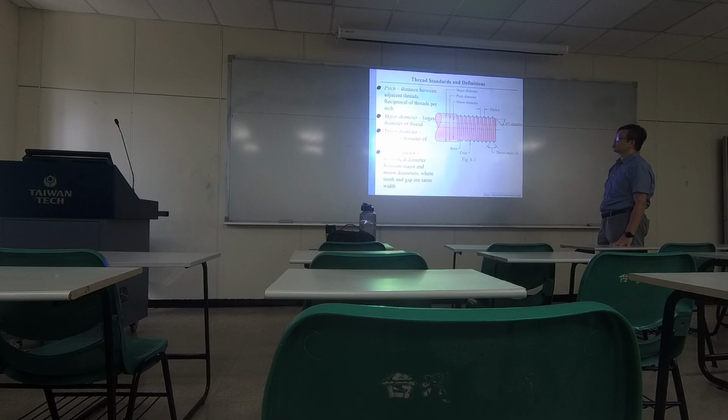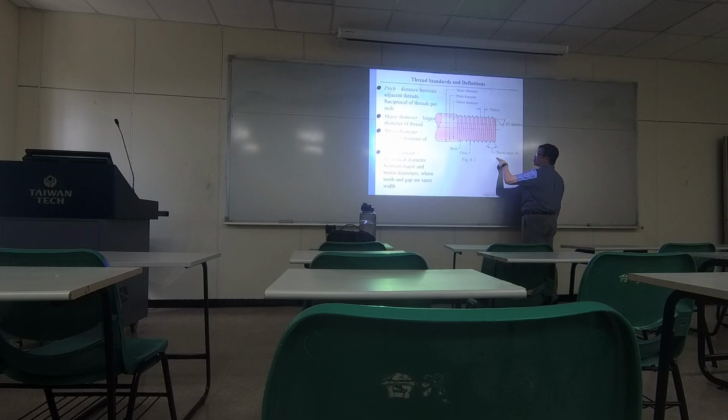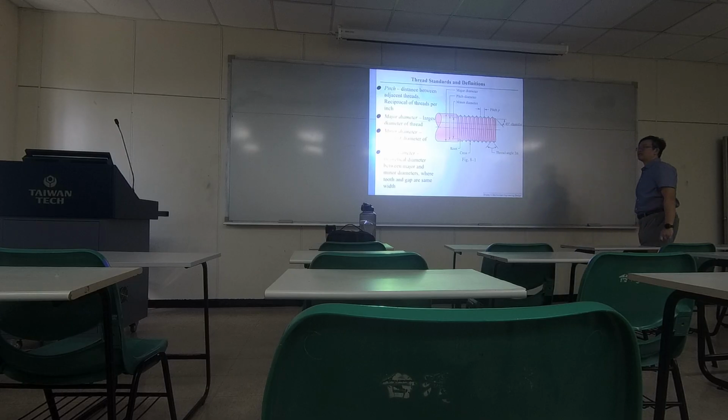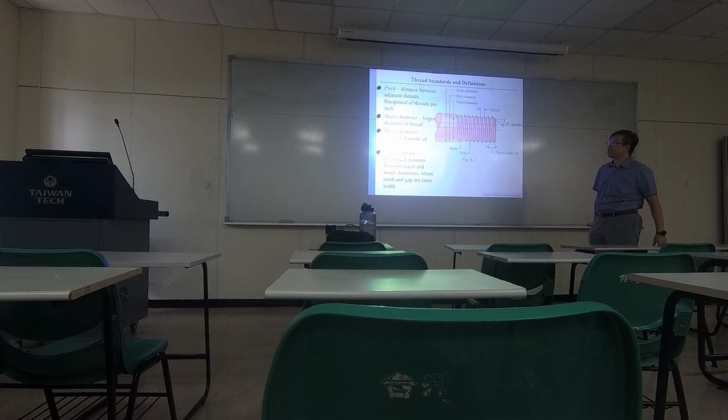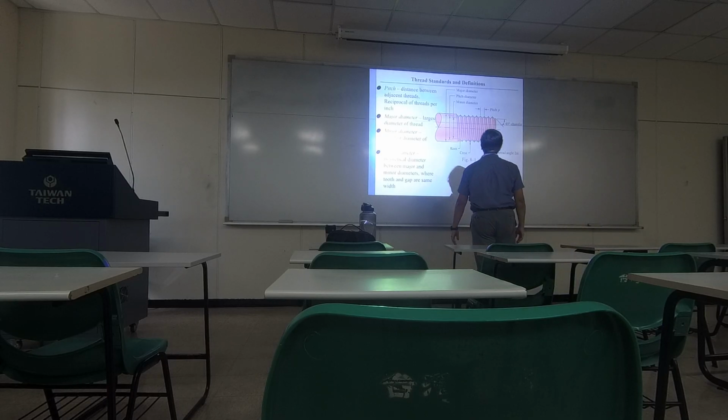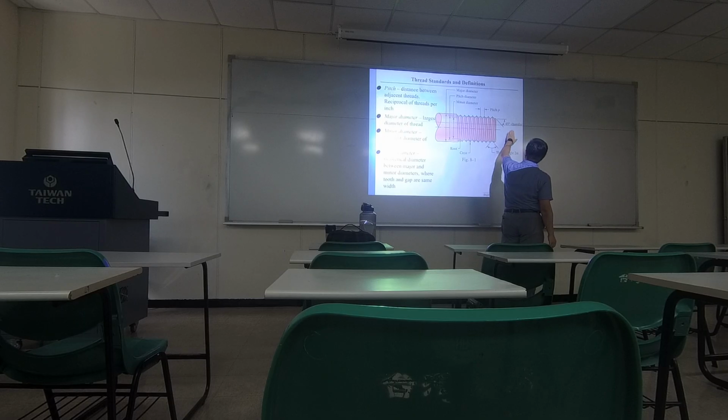So later on, when we study the forces, we assume the forces are concentrated at the point right at the pitch diameter. But in reality, the entire face of this thread is carrying the load. It's a distributed load. So it's an assumption that the forces are concentrated at one point. Okay? And usually at the edge there's a chamfer.